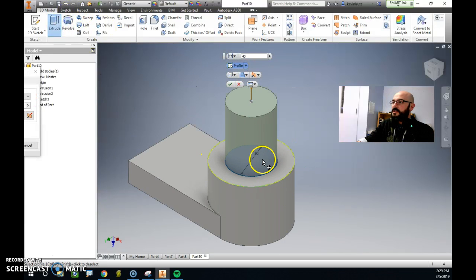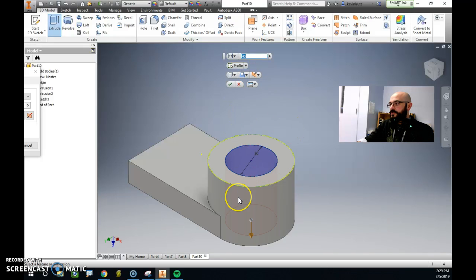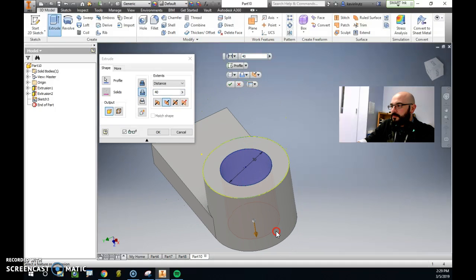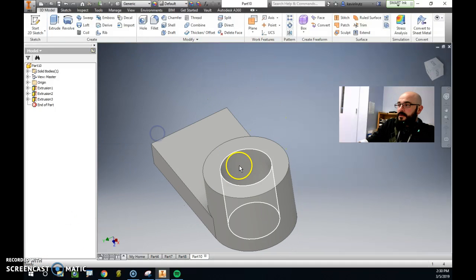You choose the object you just selected, and you're going to change the extrusion direction. You could change it to next, to, all, and it's basically the same thing as measuring the distance and using the height, but it's just other options that are available to make that hole. Now, this is a sketched feature.